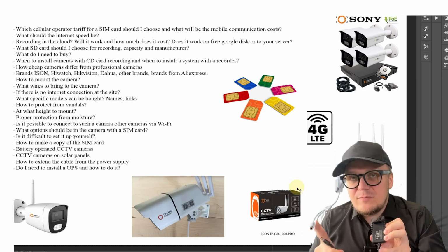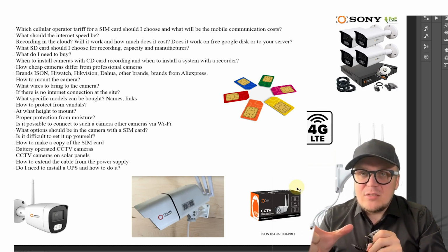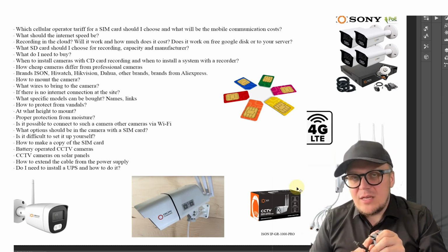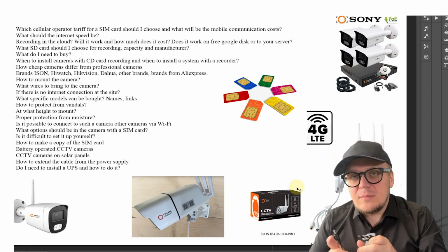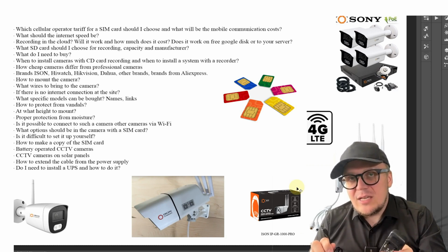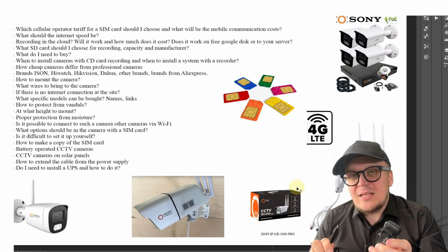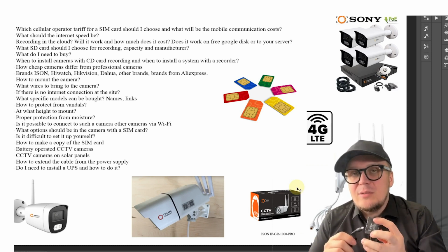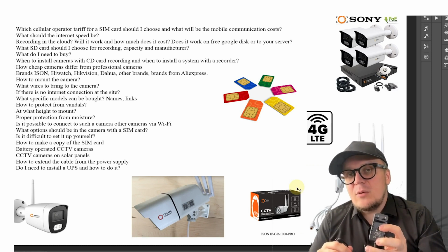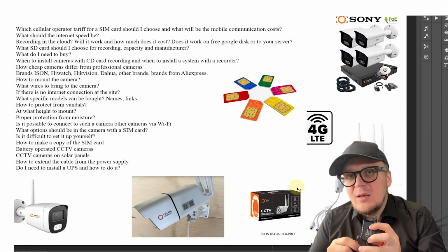And the longer this length, the more powerful the power supply needs to be. I recommend you immediately check at your site how you will power your surveillance camera, and when purchasing, ask the manager in the store. Ask whether you plan to connect, for example, 20 meters of cable to the standard power supply, or if you need to buy a more expensive, more powerful one.